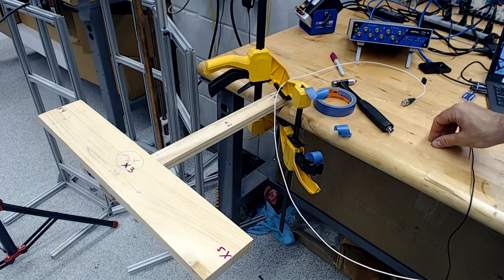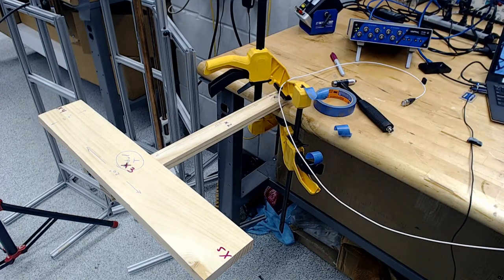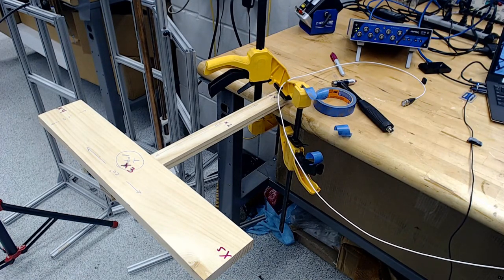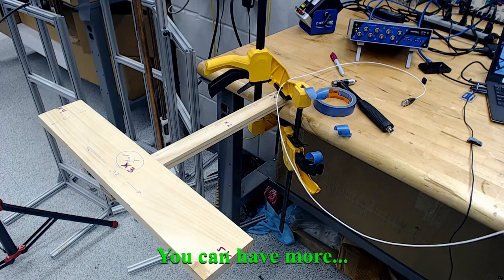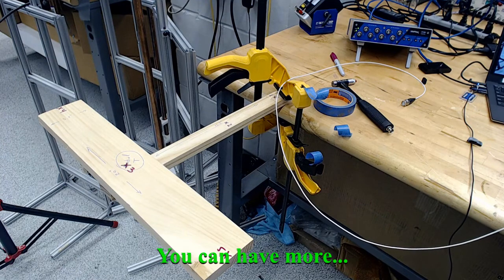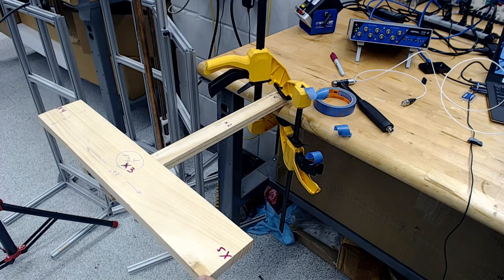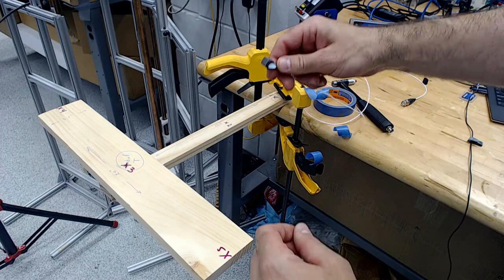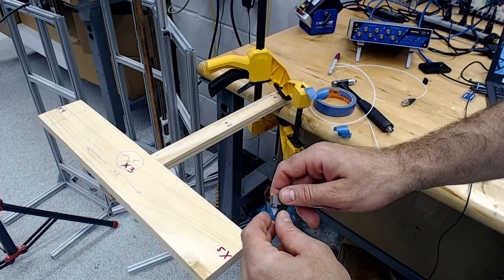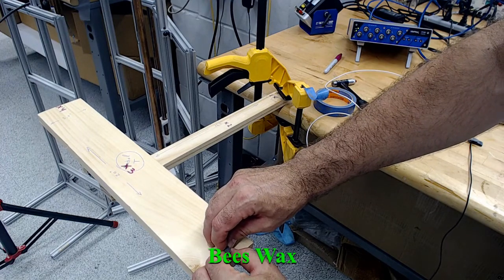Remember that for hammer test, the hammer moves around the structure and you only need one response point. So one response reading from an accelerometer. I like to put them in the places where they expect to be high responses. So not in the root, but maybe at the tips. So you can use the beeswax that comes with the accelerometer and just push it in.